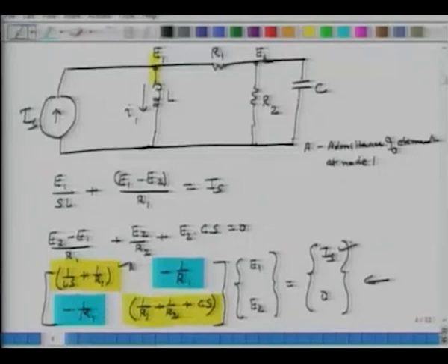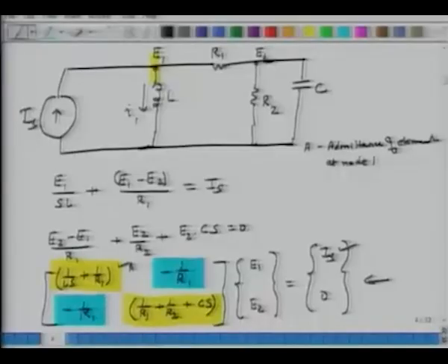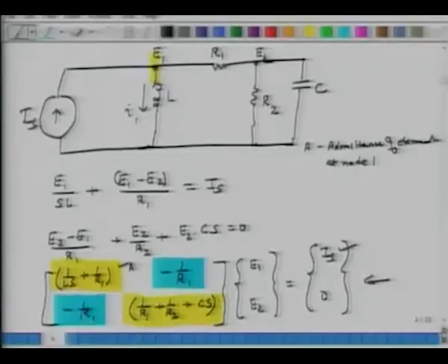When I look at the equations, I'll say, oh, there's a current source here. So I'll put a current source. Then I will say it's a 2 by 2 matrix. So there are two potential nodes in the system. So I'll put 2 dots. Then I will say what is the impedance of the 2 nodes which are connected to each other. So I will say that the admittance, when I look at these blue boxes, is 1 over R1. So I connect them by a resistor of value R1. Right. Then I say at node 1 I have 2 elements, an inductor and a resistor, and they are in parallel.